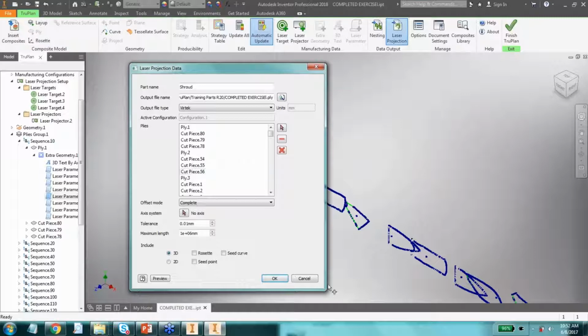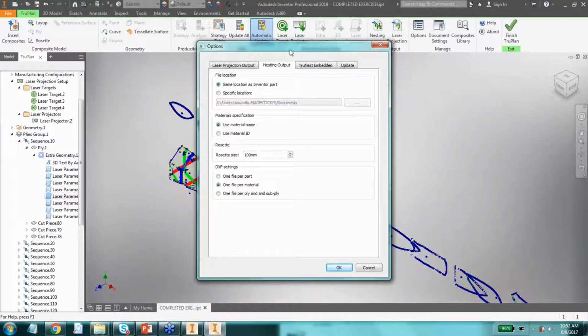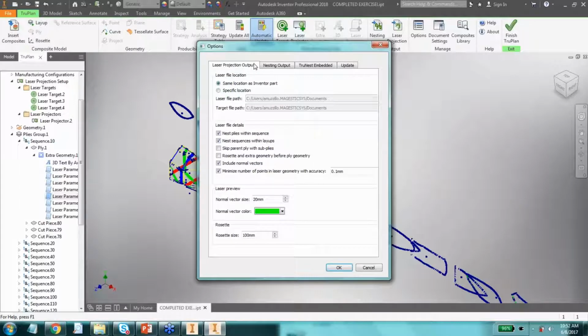One of the things that comes along with that is not just the simple points themselves, but also what we call our normal vector. So the point is determined by an XYZ location. For each point, we also include what's called an IJK vector. And so that describes where this point is, but also where the surface of our tool is behind that point.